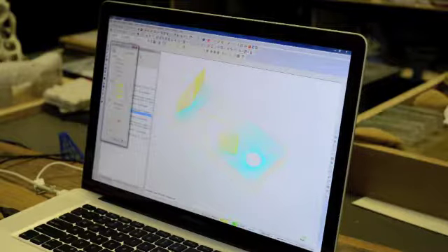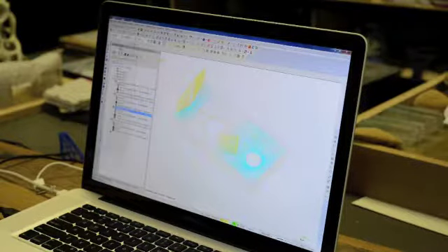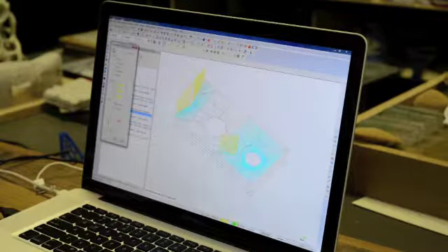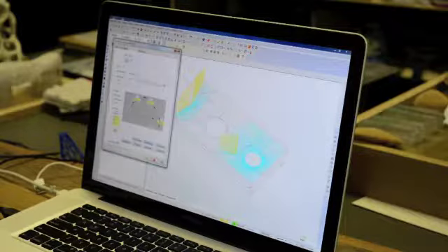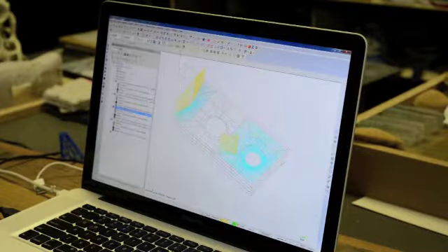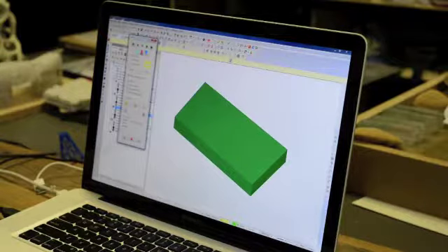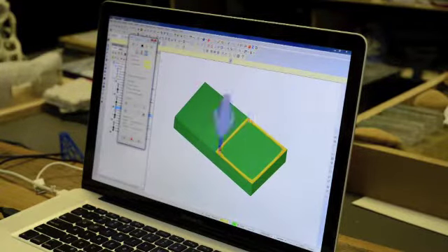And what you do is pick that box that we had drawn in Rhino as our bounding box, press enter, leave these as they are, hit OK, and you go up to our preview, you can see that it made the stock exactly the shape of our material. You can run it.